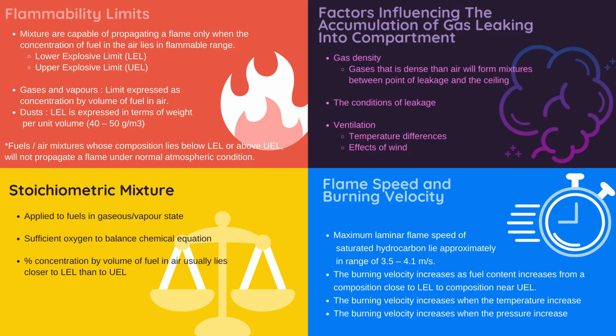Burning velocity can be defined as the velocity at which the flame front moves relative to the unburned mixture of fuel. The burning velocity increases as fuel content increases from a composition close to LEL to a composition near to UEL. When the burning velocity increases, the temperature also increases. Lastly, the burning velocity increases when the pressure increases.